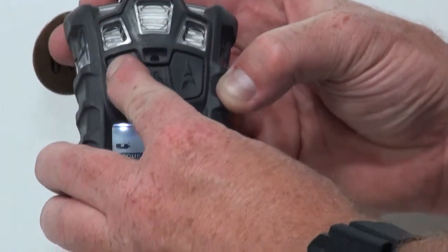So to determine what those levels potentially were at depth within the space, we have to access the peak modes on our monitor. All monitors should be equipped with the ability to scroll through screens so that you can see both minimums and peak readings based on that time period. Once you've evaluated what those peaks were, you should have another button selection that allows you to zero those peaks out. So document what your peak was at depth, record it, and ensure as you're advancing the monitor and withdrawing the monitor that you are doing it at a speed or a rate that's commensurate with the sampling time of the monitor.